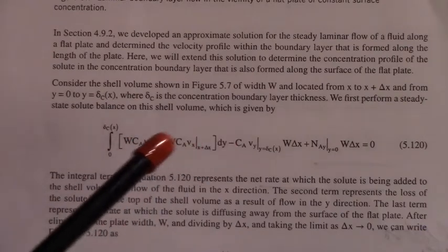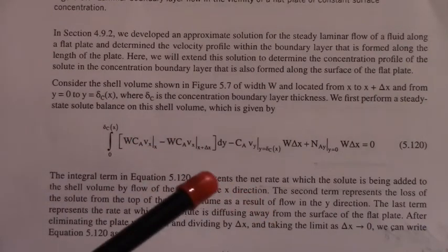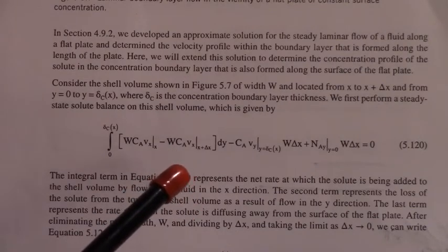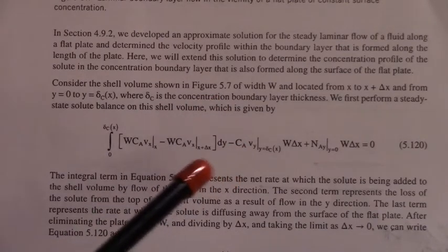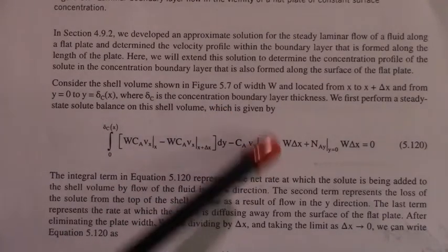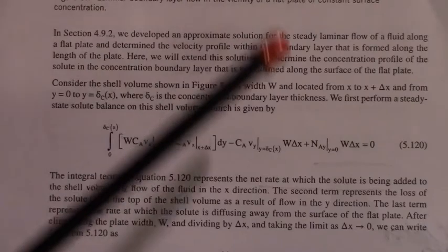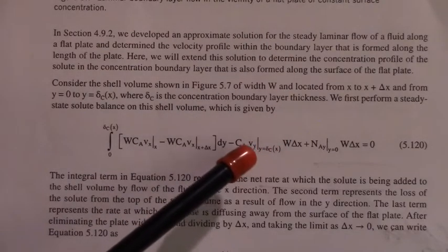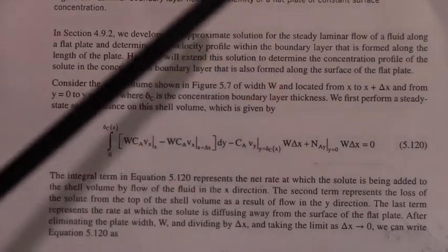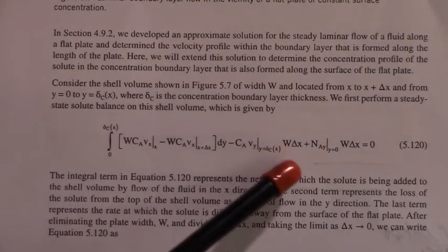So remember, these equations have to talk to you. You have to look at each term and reconcile what those terms mean in terms of the physics of the problem. Also, we know we have a velocity up here at the top of the box, and that velocity is going to be carrying solute with it, and the area that's normal to the top of the box up there is W delta x.